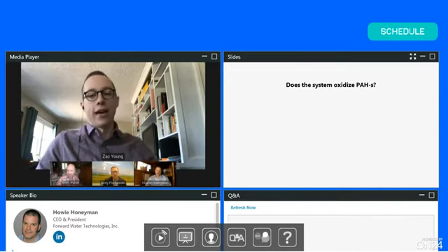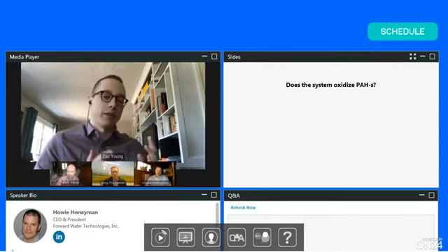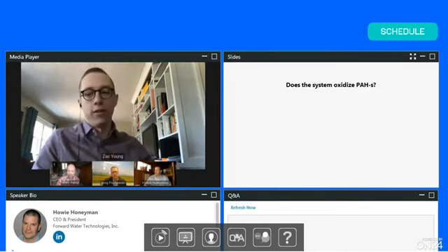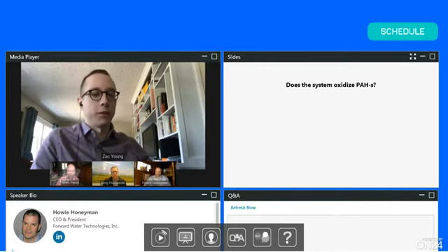So yeah, PAHs are certainly addressable by a photocatalytic AOP. In fact, one of the things that may be of interest to people on the chemistry side is that we're generating a mix of oxidants, so not only hydroxyl radicals, but also superoxide radicals from dissolved oxygen in the water. So there actually are some reaction pathways that are particularly well suited to this application, and so absolutely treatable, yeah.